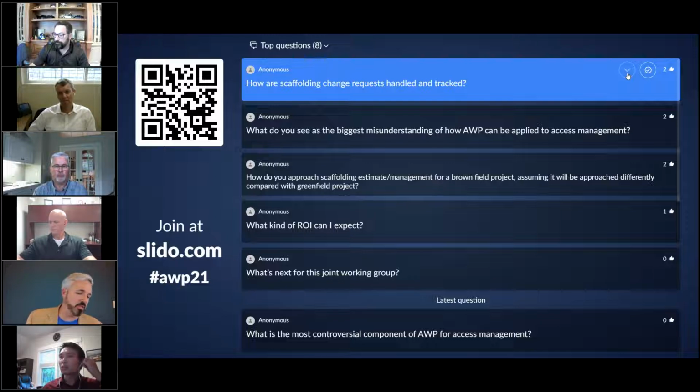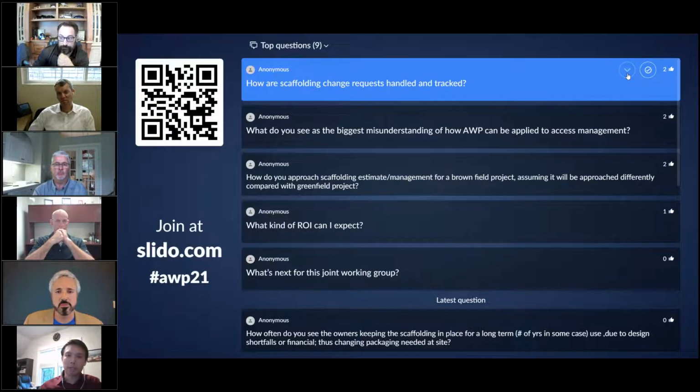No, with scaffolding, do you have a false sense of performance early in the project that then falls apart late in the project? Yeah, and I can give some examples of this. Let's say you're building a very tall structure, let's say a coker tower. A lot of your effort is going to be spent up front building the initial access to that coker tower, and then you're on a very steady course of small modifications throughout the life of that job, and then towards the end you have all that effort to take that scaffold down.